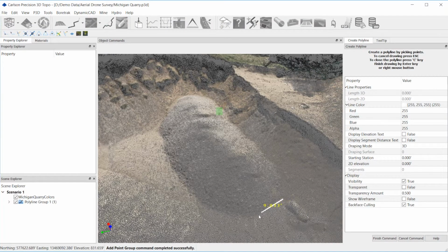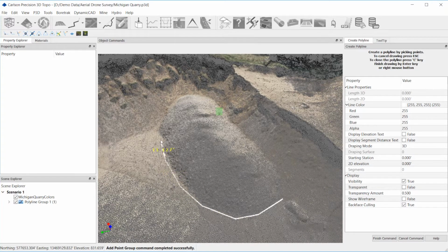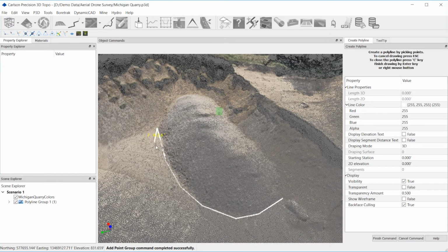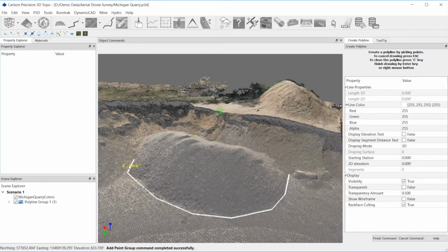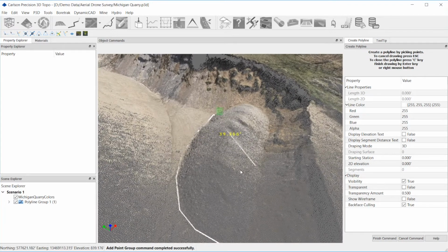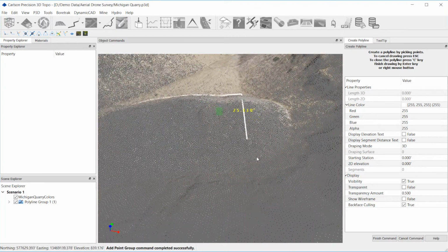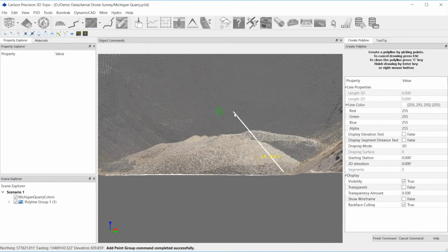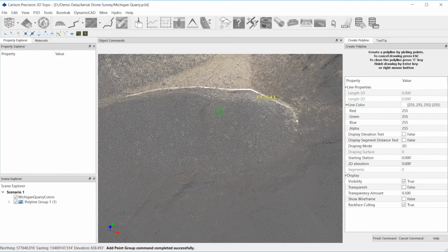And so what I'm going to do is start to draw a polyline, and I'm going to just pick out here around the pile, like we normally would around the toe. Now when I get up into this area, this is where it starts to encroach. But what we want to do is measure the dirt under here and capture the pile. So I'll try to rotate around here a little bit so you can see what is going to happen, and that is I'm going to set the planar snap to snap at a fixed elevation underneath this area.